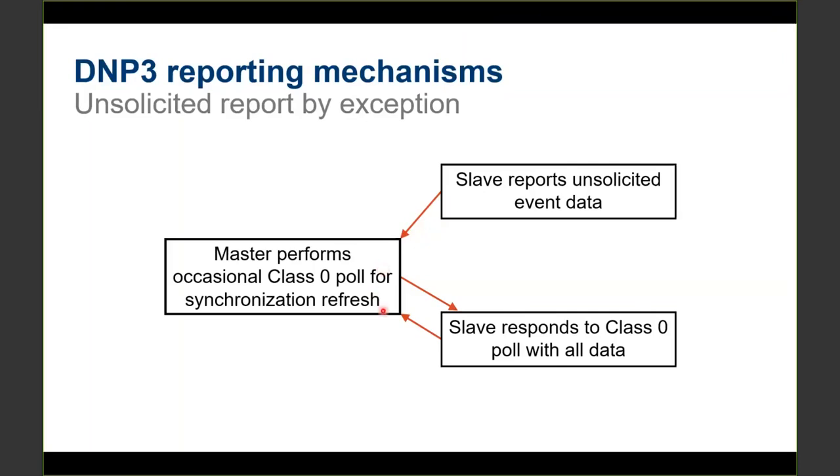Collisions are caused by 2 or more slaves sending events at the same time in a multi-drop connection or point-to-multipoint. To get around this problem, the protocol provides the possibility of retransmitting unsolicited messages. So we can define this retransmission period in each slave device. But one more time, keep in mind it's really recommended for low bandwidth applications with point-to-point connection.